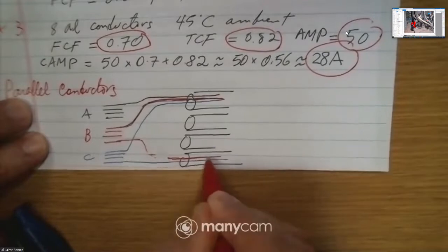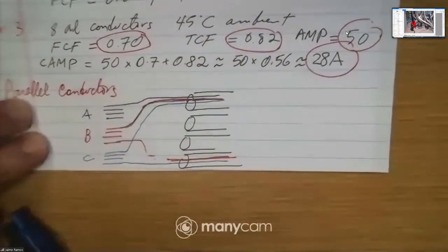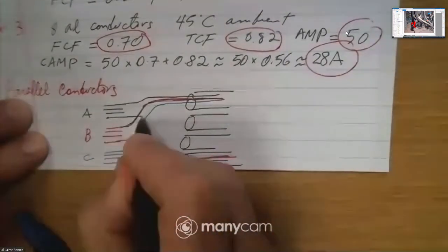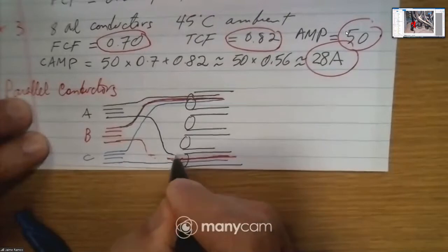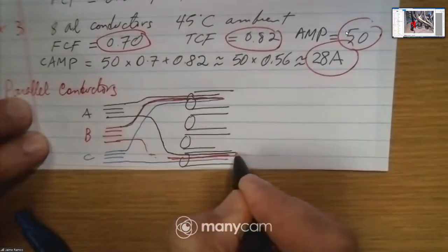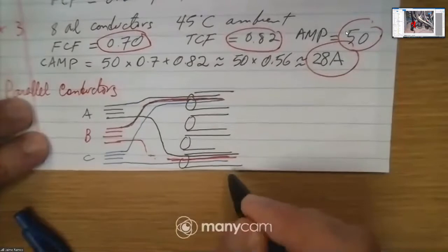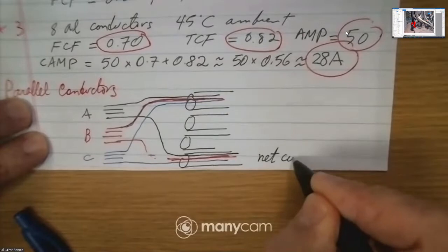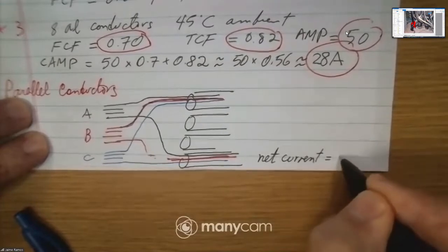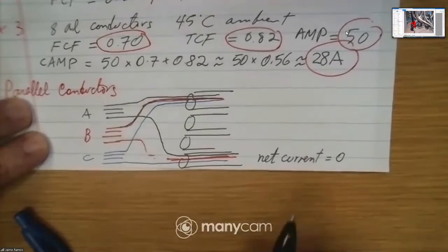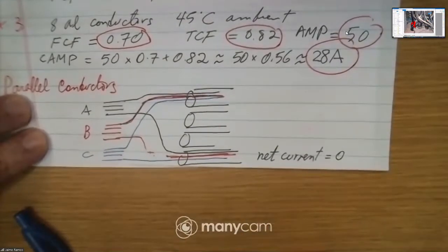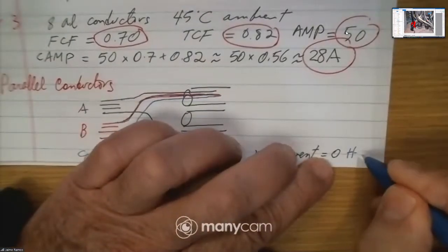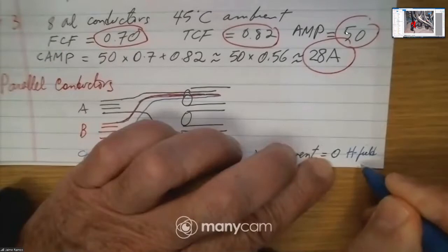What's the reason for that? For not putting them together. Yeah. Okay, the reason is that, look, as we put them here, as now I'm showing, the net current within the conduit is 0. Okay, do you agree on that? Yes. So therefore, the magnetic field, H field created by that is 0.